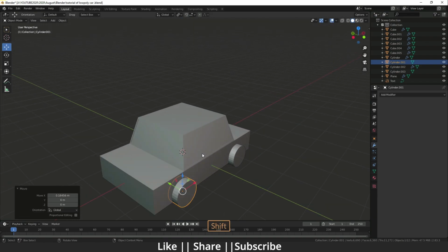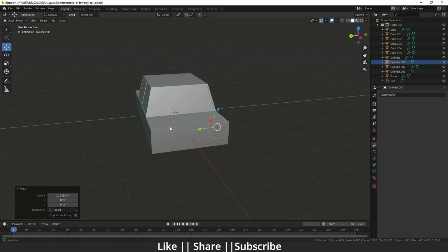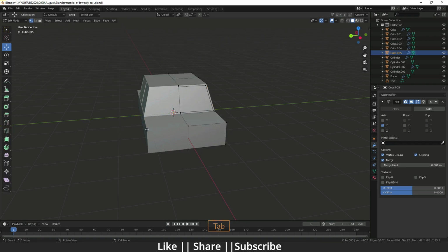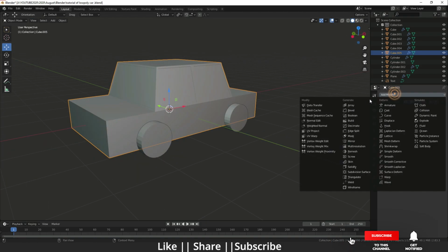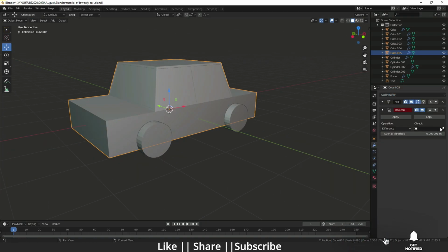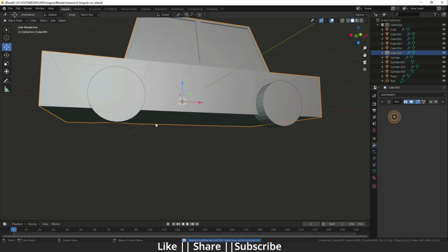Okay, so now we are going to do boolean. So make sure whenever you do boolean, do not boolean to the mirror part, because if you do the boolean in the mirror part, you will not find anything. So make sure your boolean object should be in a mesh part, not a mirror part. Okay, so now I'm just going to add the boolean modifier, and I'm going to select that cylinder, and I'm just going to apply.